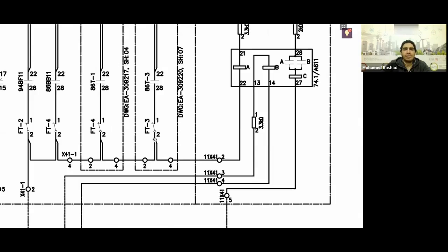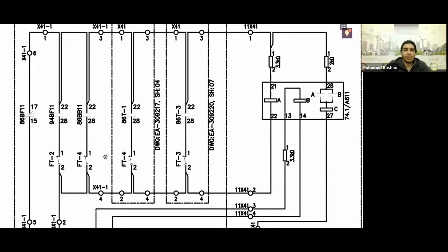Excuse me, Bashar, could you please explain to us what these things are? Why didn't it go to the contact itself? What are these things? These things are not French. They are a finger type switch like ABB, for example. This finger type indeed is your test switch for situations when you are conducting tests or performing a trip test or doing anything on the protection relay and you want to isolate your trip circuit. So always all the turbine contacts are isolated through the test switch itself.